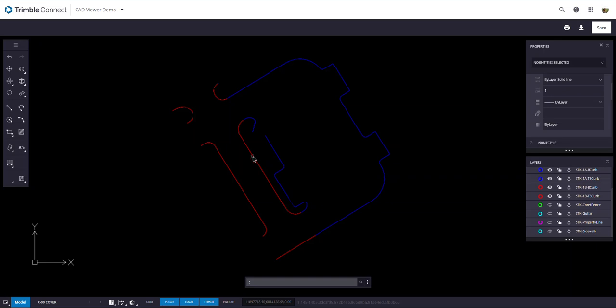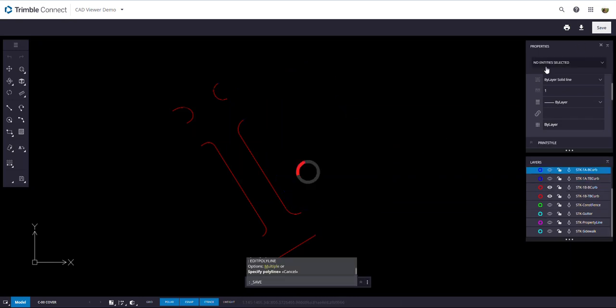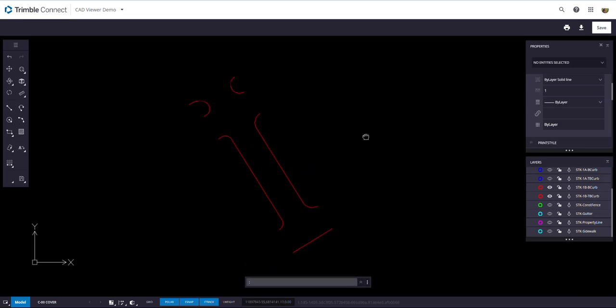So now we want to work on the 1B lines, now that we got all the 1As completed. So we're going to go turn off the 1A line layers. We're going to turn those off. And you probably want to save. This is a good time to save. Again, getting in the habit of saving often. Otherwise, like I said, if it locks up, you're kind of stuck.